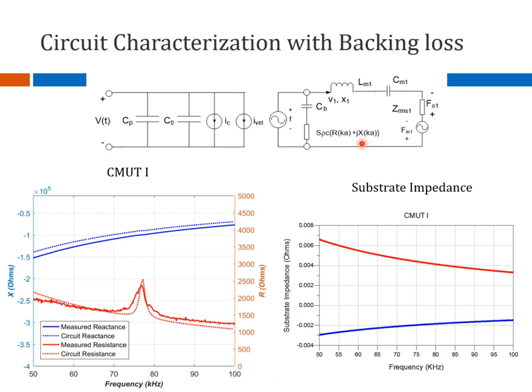So the important thing is that you have to model it properly so that it can be explained in the model, and you can then go ahead and measure the received performance of CMUTs as receivers or even in transmitters. So the transmitting voltage response or the receive sensitivity of a CMUT is going to be affected by all the losses that go into your model.